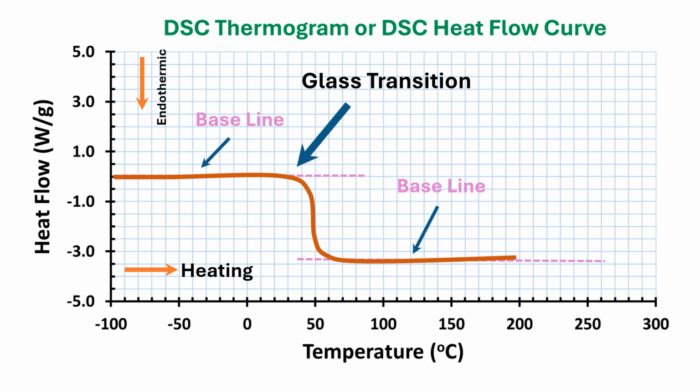In ideal cases, the shift should be at a constant temperature. However, in reality, glass transition occurs over a temperature range. In this case, onset, mid and end of the glass transition temperatures are recorded. The change in del Cp at this transition is also estimated, and it indicates the characteristics and fraction of amorphous in the sample.